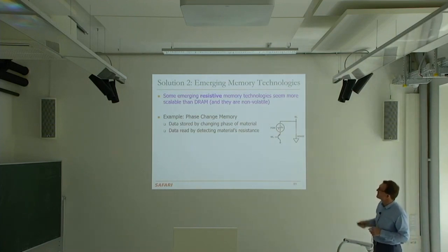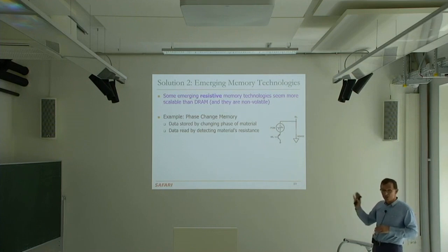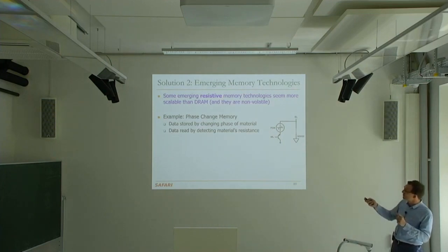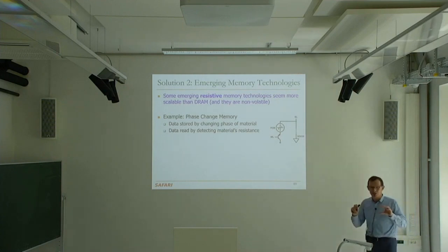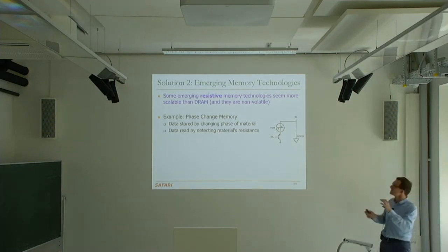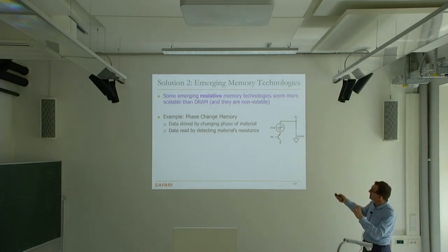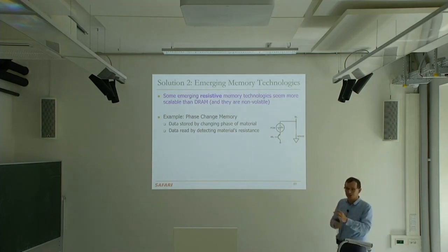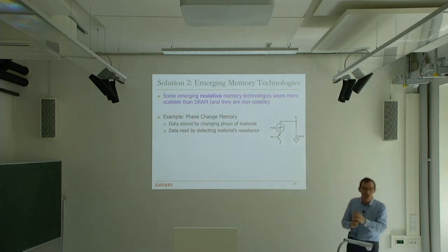And it gives you different data based on how it reflects the light, based on the resistance that's inside here. But now it's very interesting because people figured out, so this is very instructive, I think. Basically, people knew the beauty or the importance of the storage device very well. So the storage device is this chalcogenide glass, for example, the resistive device. But the access device is extremely important also. If the access device is really slow, you cannot use it as main memory. And in rewritable CDs, the access device is light-based, essentially.